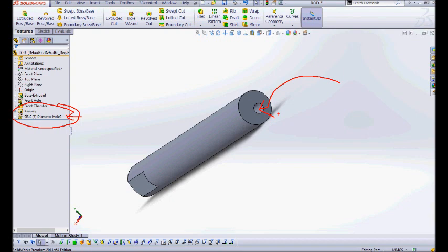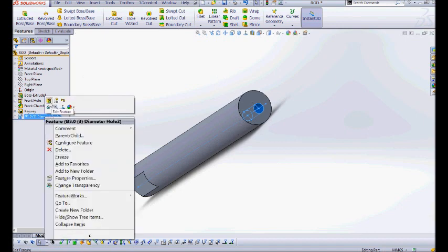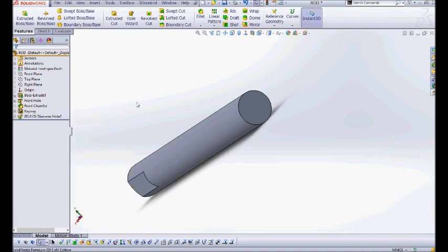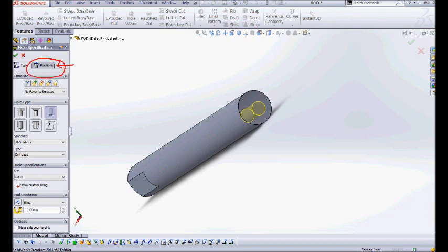Select the front hole in your browser, so you can just highlight that hole, and then go Edit, Copy, and you can also press Control C, right? And then orbit over to the back face and go Edit, Paste. It'll give you this dialog box asking if you want to delete relationships. I'm just going to say delete them because I'm going to recreate them.